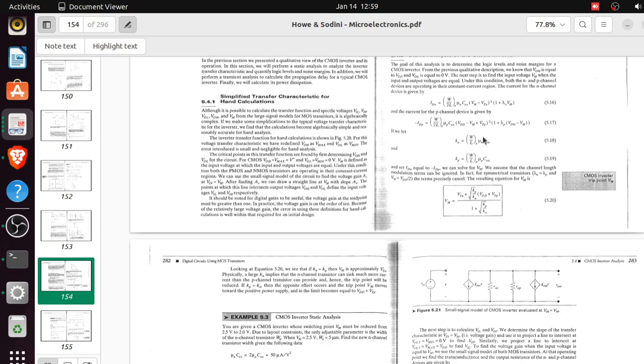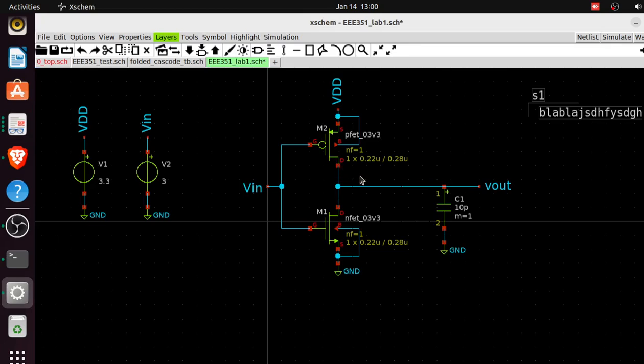When we did further breakdown, we notice that it means the sizing for PMOS must be twice the sizing of NMOS, which makes sense physically. What's the physical implication? You have the PMOS and the NMOS. By mobility, electrons having more mobility than holes, it means NMOS will be quite faster than PMOS. So you're putting two things with different speeds together. So what do you need to do?